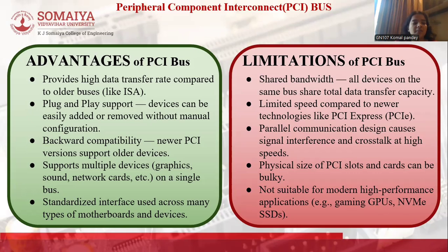However, the PCI bus does have limitations. Because all devices share the same parallel bus, the bandwidth is divided among them. At higher speeds, signals can interfere or crosstalk, reducing reliability. This is why the industry gradually moved to PCI Express, which uses dedicated serial lanes for each device.